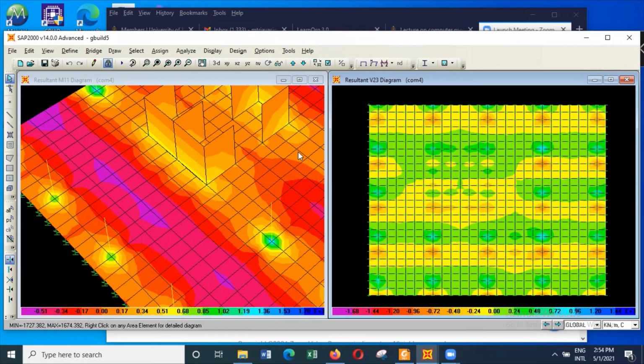When you are finding the reinforcement, you will add the bending moment and the torsional moment and find the reinforcement. When the torsional moment is significantly less than the bending moment, you can just add them. Otherwise, you have to consider the sign and add it carefully, as we have done in the examples that we discussed in great detail, covering all the possible scenarios.